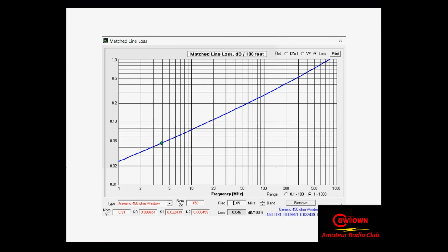One of those compromises is he trades off some noise for efficiency, and in his case, the way his antennas end up designed, the window line very easily becomes a part of his tuned antenna. So it makes it easy for him to say, okay, a little bit of math for this frequency, I need to add 6 feet of window line in series, and that'll tune my antenna. It's a trade-off.